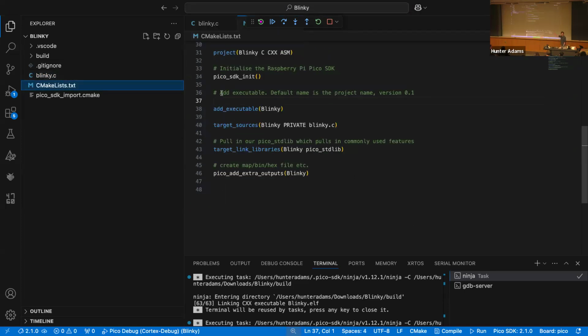And in the next demo that we look at, we'll see an example of this. This too, if you forget to do that, you'll all forget to do this because it's the easiest thing in the world to forget. The compiler won't throw an error, it'll throw you a warning where it'll look at the C SDK function that you're attempting to use and tell you it's doing an implicit definition of that function. What that's telling you is, I don't know what this function means. And that should make a little alarm bell go off and go, oh, I forgot to modify the CMake list